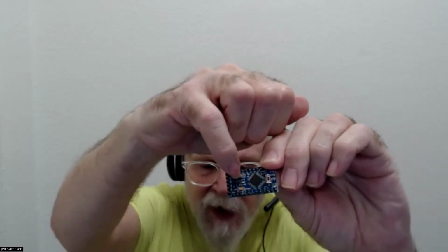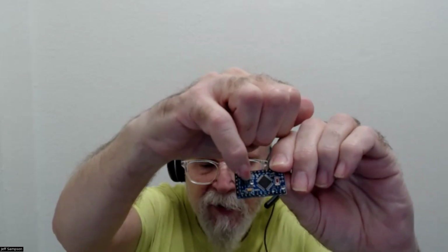And it turns out that if you want even less power, they're saying either pull the voltage regulator off the board, which is just one of these little tiny chips here, like 5 pins on it or something. It's microscopic, but you can pull that. They pull that off the board and then feed the power just into the VCC pin. And I think at that point, when they put it in sleep, it got down to 7 microamps, which is almost nothing, but that's just something you can do with that.